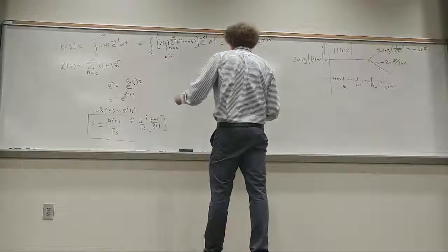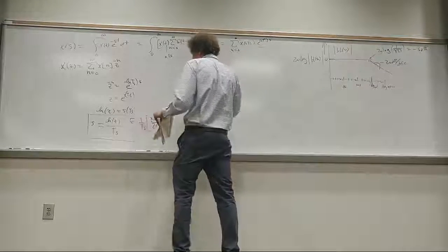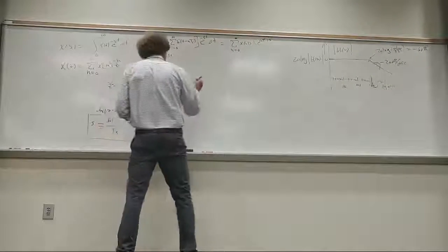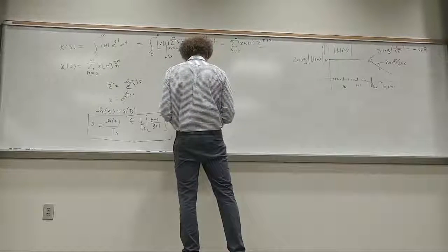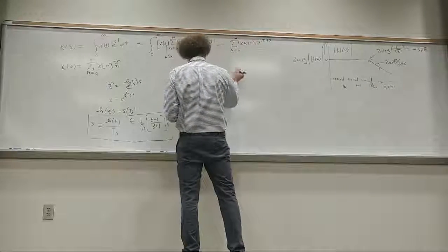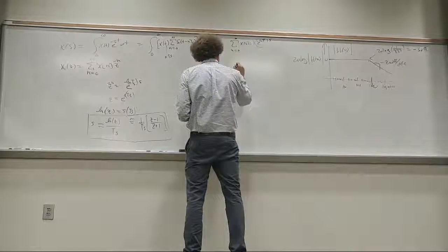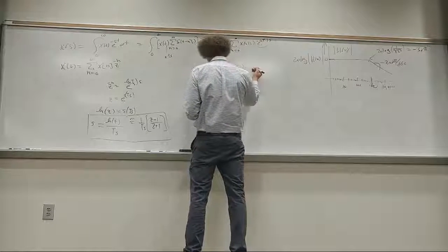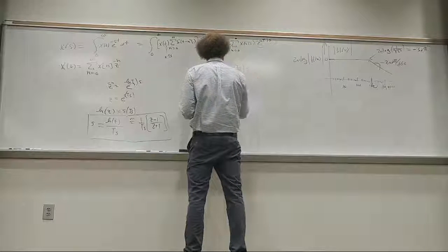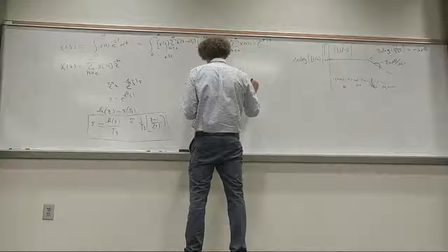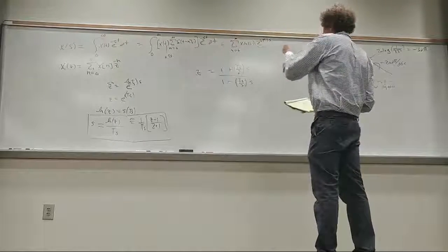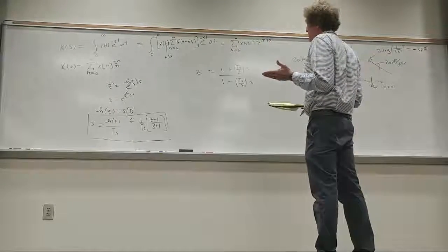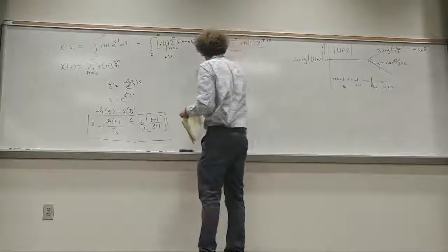So now, if I have that, remember, this is for s. Then I can say z, based on the second part, can be rendered as simply 1 plus Ts over 2 times s over 1 minus Ts over 2 times s. And again, this is a simple relationship between z and s.